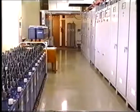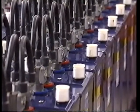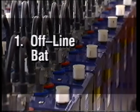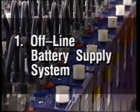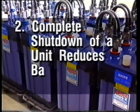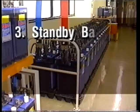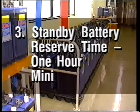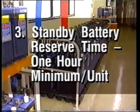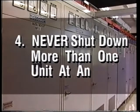Let us stop here and revise the important points to remember about a buck-boost power supply. 1. It is part of an offline battery supply system. 2. Complete shutdown of a unit within a system will isolate that unit's standby battery, significantly reducing the combined battery reserve time. 3. Each unit has a nominal standby battery reserve time of 1 hour minimum. 4. Never shut down more than one unit at any time.